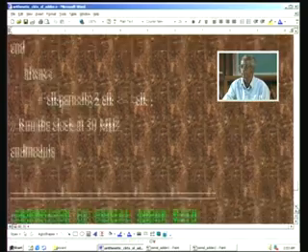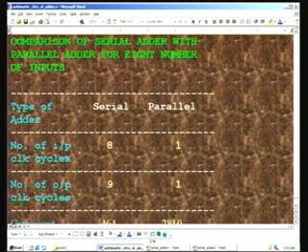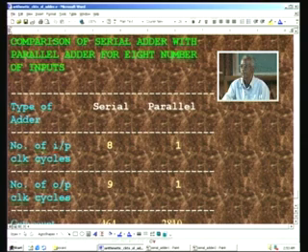This is the end of the test bench, and we will have a quick glance of what a serial comparison between serial ladder and parallel ladder looks like. For a serial ladder, which we have already considered, you require 8 clock cycles for inputting n0 through n7, whereas in parallel, in one stroke, one clock pulse, you can do that. And similarly, the output will take 9 clock cycles, because after having input all the 8, we had to make the enable low for one clock pulse, then only the sum will be cleared, and that is the reason why one additional clock cycle is required.